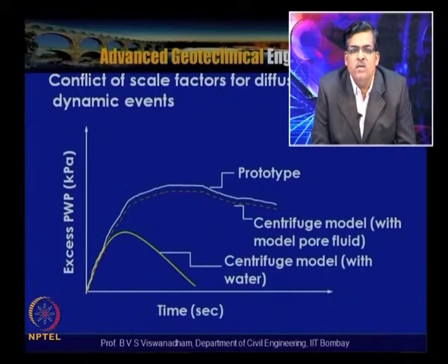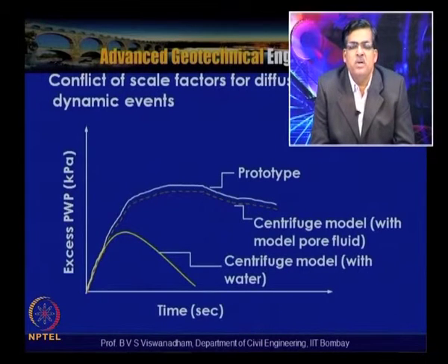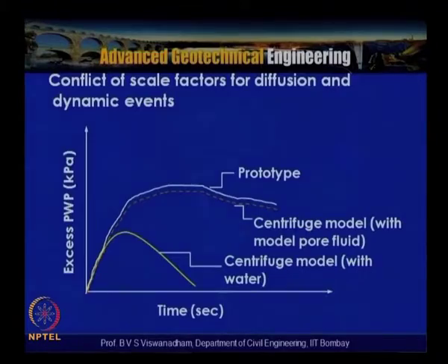Then we said that a number of different types of pore fluids have been used, but one thing is that we have to see that the pore fluid will not affect the strength properties, and also will not alter the constitutive behavior of the soil and also the damping characteristics.